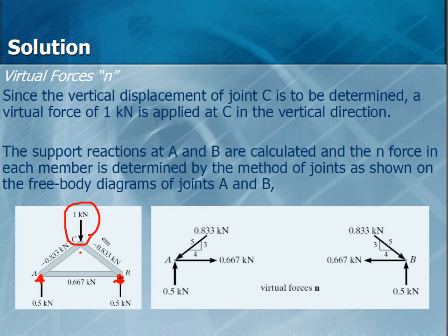Now in this method, we have to differentiate between tension and compression. It is recommended to use a sign for them. You're going to use the joint method to find the member forces. First find the reactions. We're assuming two analyses. One is the same truss with no external load, you remove it, you apply the load in the direction of the delta, and you analyze it. Analyze means that you find the member forces.